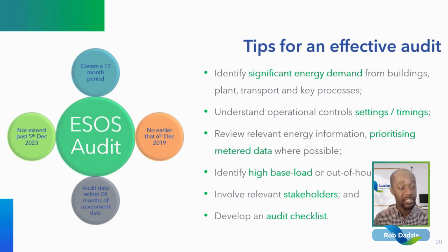Review your BMS schedules. We often see that there's a poor handover, particularly with new builds, between the final stages of construction and operations, where the operational team aren't aware of the settings, the set points, the timings that are being implemented, and they don't know how to optimize building efficiency. Or they have an FM provider, and the assumption is that the FM provider has optimized things for them, but things haven't been checked on a regular basis, and therefore your building's running inefficiently as a result.